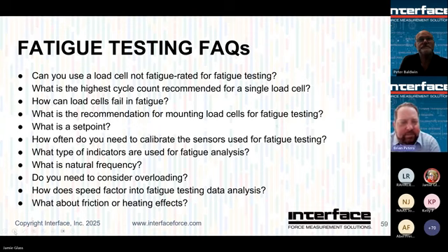All right. What is natural frequency? If you think about natural frequency of these load cells, we showed you an example earlier of the 1200 series. Different capacities had different natural frequencies, but electrically, you can look at it as a low pass filter. So everything below that frequency can be registered by the load cell. Going back to the mechanical reference, it's a spring that starts to get out of control if you start oscillating too fast. So, as we suggested, good practice is going to have us pretty far away from the natural frequency. But it's not to say that you can't start to push that.